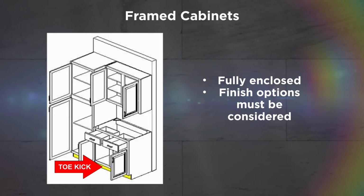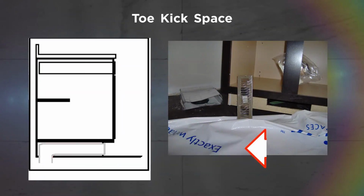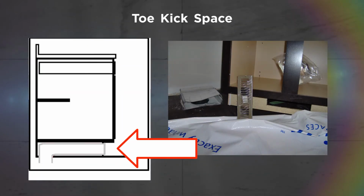It is your responsibility to order plenty of toe kick for the project. Now, the toe kick typically comes in 8-foot lengths to be attached by the cabinet installer after the cabinets are in place. Remember, the toe kick area underneath base cabinets is open and can be used for mechanical access. For example, water lines to refrigerators can run through this space.